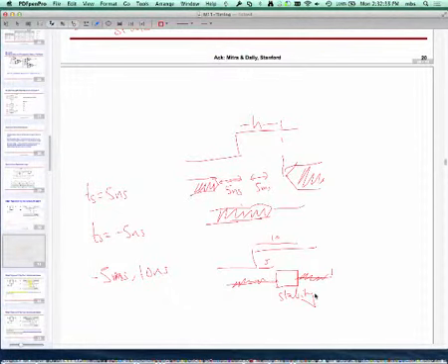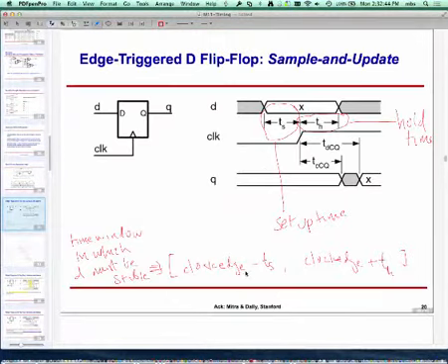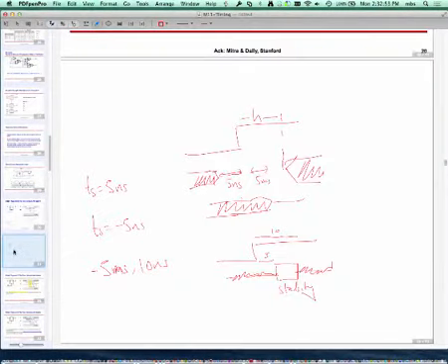Now, the setup and hold values will always be such that this stability time is something positive. Okay, so you would always see that, going back out here, clock edge plus TH would always be later than clock edge minus TS, even if TS and TH are negative. If hold time is negative, so let's say I consider a flip-flop which had a setup time of 10 nanoseconds, and so this is S, this is H, setup time of S and hold time of minus 5 nanoseconds.